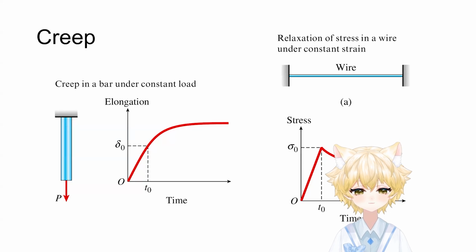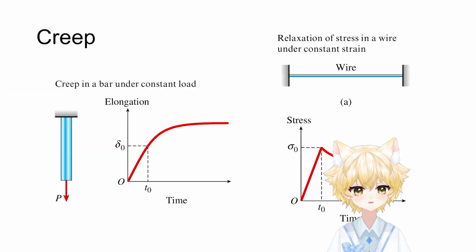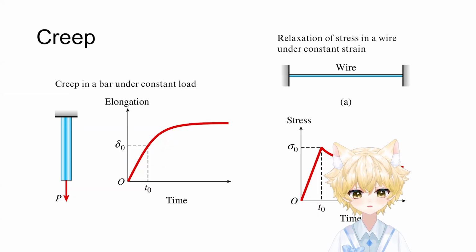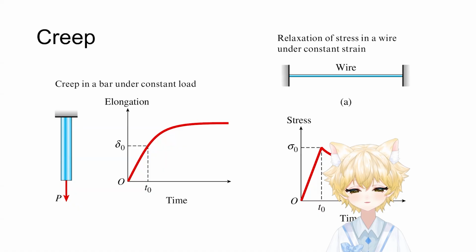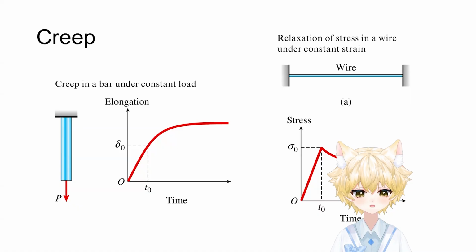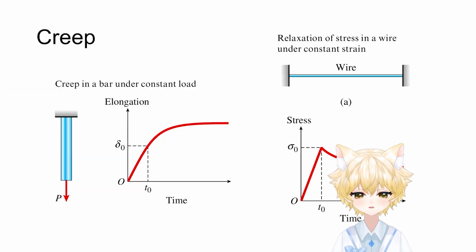For those kinds of power lines, over years of handling under their own weight, the wires physically get longer due to the creep, causing them to sag dangerously lower. This is why these materials have an expiration date. They aren't breaking, they are just slowly, inevitably changing shape until the shape is unacceptable.